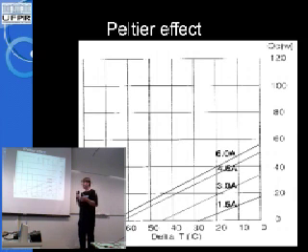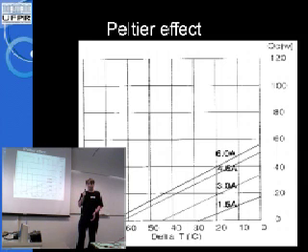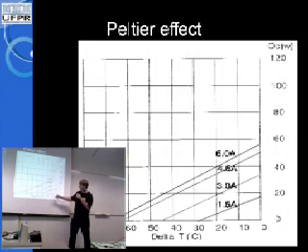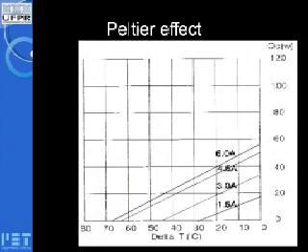But if we could apply, let's say, 1000 amperes on a Peltier effect cooler, we couldn't have a difference of temperature so big. So most of the Peltier effect coolers have a maximum difference of temperature called delta T. Let's say at a difference of 0 Kelvin, it pushes, let's say, 58 watts from the cold side to the hot side.